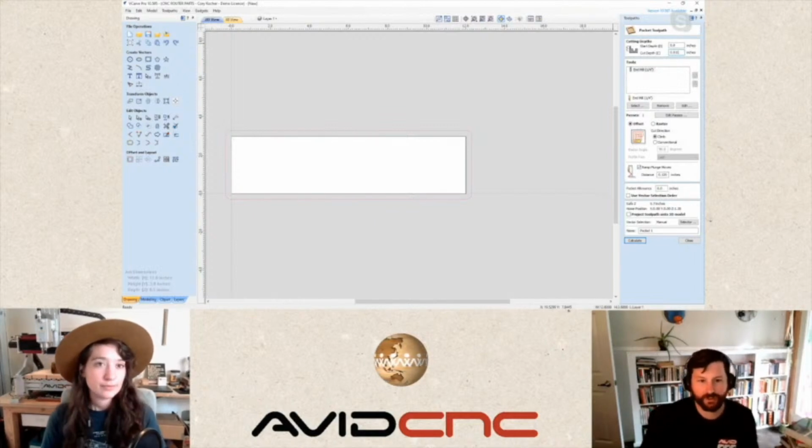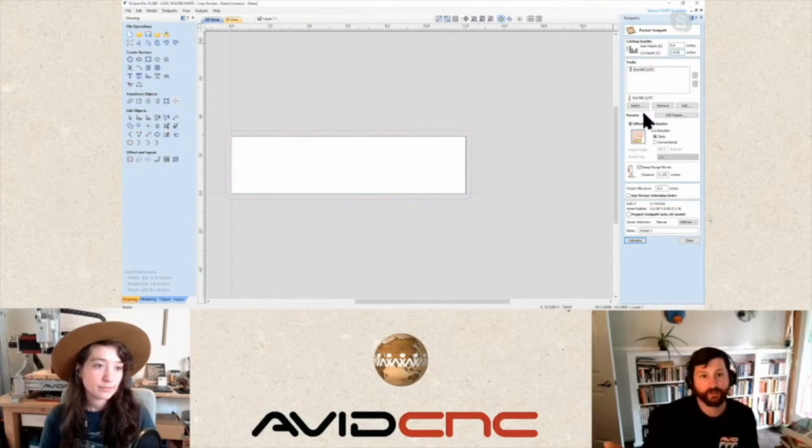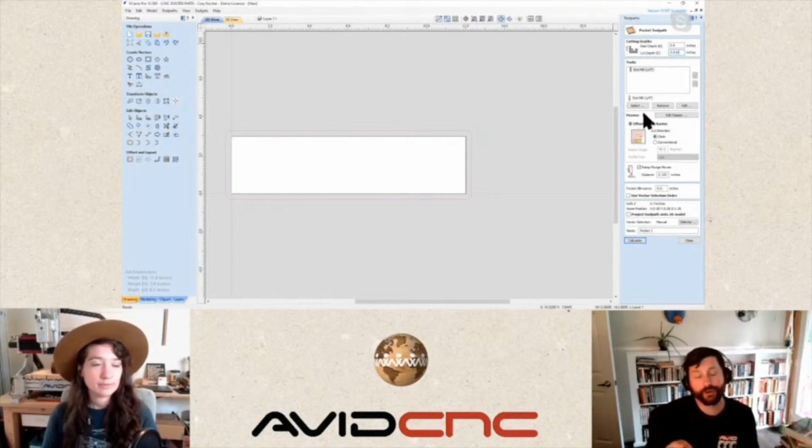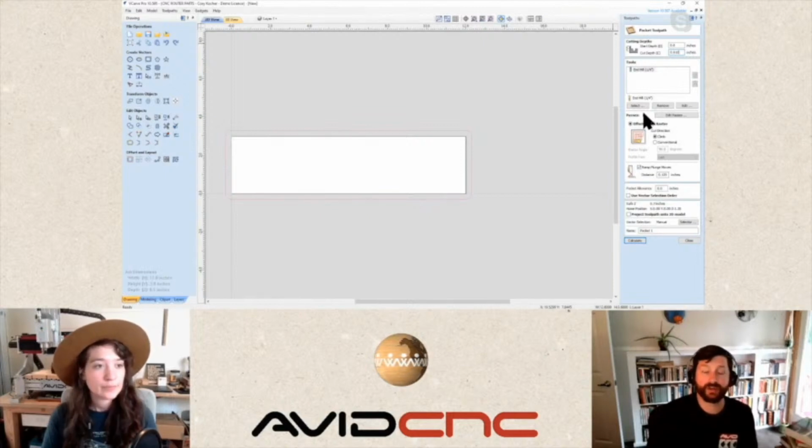So we're just going to go down and surface that top material. When surfacing, sometimes you might have to go through a toolpath once, twice, or three times, depending on any voids or inconsistency with your material or your work holding technique. If you find that when you're surfacing only half of your material is getting engaged with your tool, your work holding might actually be holding your material blank at an angle to the gantry. So we're going to do a cut depth of 10 thousandths, so we're just going to barely kiss this material.